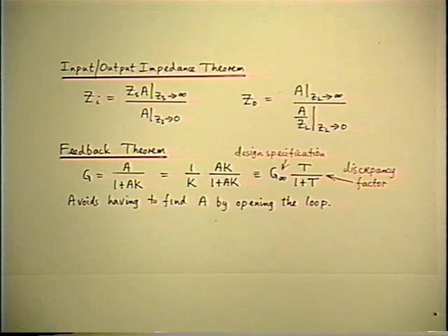So what are we going to do about it? Well, this is well recognized, of course, and the way most of us get taught to handle it is we try to fudge the loading after you break the feedback path. You try to guess what the loading is, and you simulate it by putting a dummy load across the forward path, which is supposed to represent what the real feedback path does to it. And this may help. But if you really pursue that idea, again, you find yourself getting into fuzzy areas where you're not quite sure just how to represent that loading.